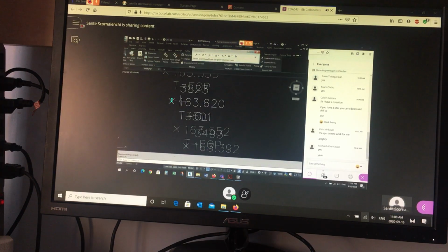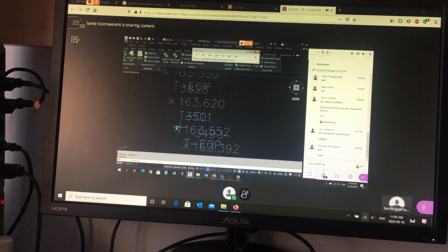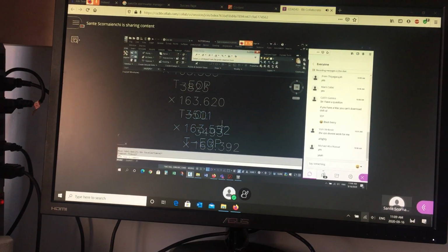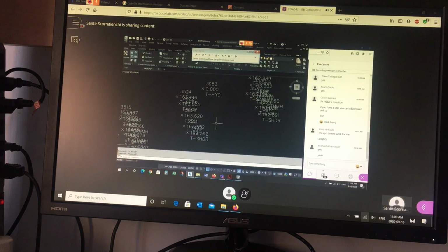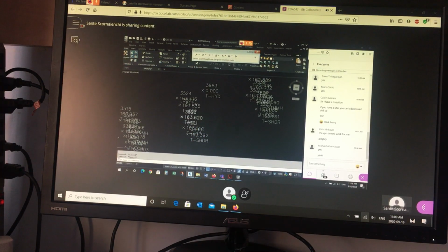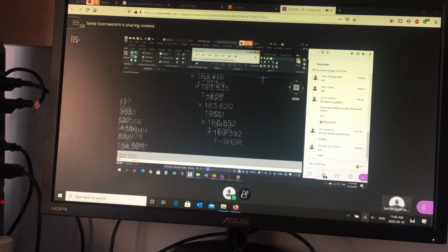So this one here, if I just pull it away, oh, that's the center line, maybe of a road. This one here, oh, that looks like EOP, edge of pavement. Maybe this one here is a shoulder. So it looks like I've got a rural road: center, pavement, shoulder. I want to isolate the layer. I just want to look at just the points that are for the center line.